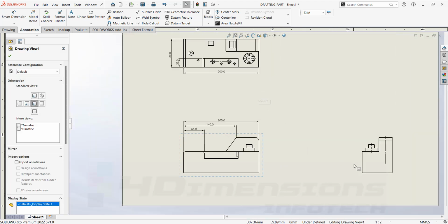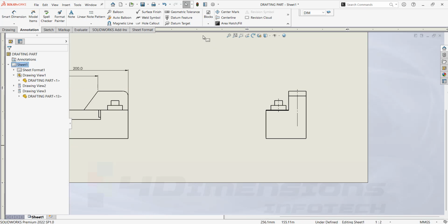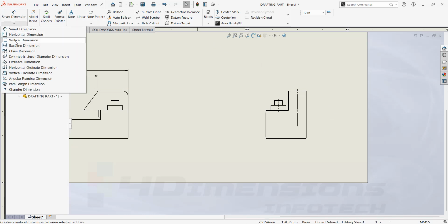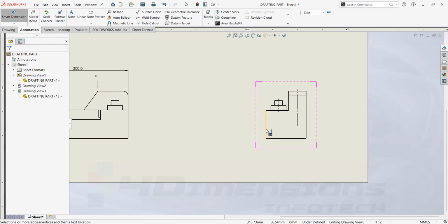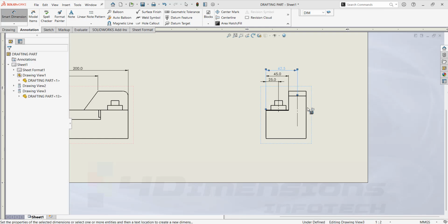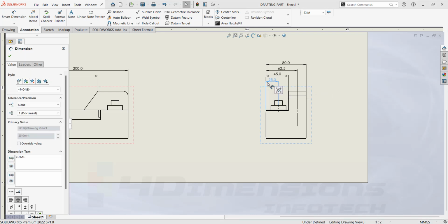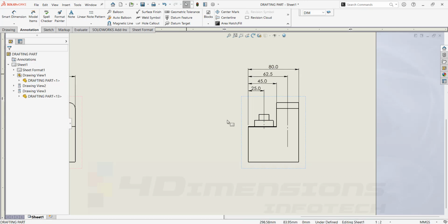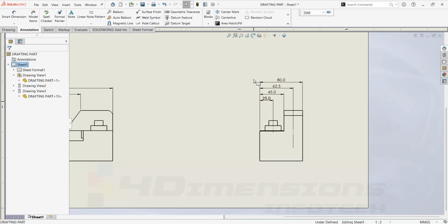Again, we'll show it here also. So here also I'll go for baseline dimensioning. Select the base first, then this axis, then this end side, then the second axis and then the last face. All of the dimensions are having one common base or datum and then followed by the ends differing at each end. Say OK. This was baseline dimensioning.